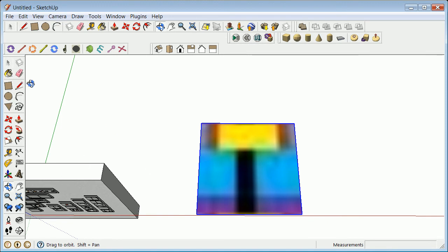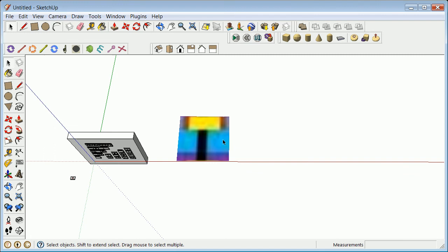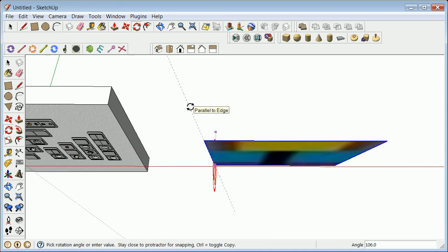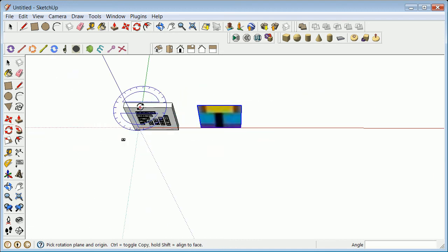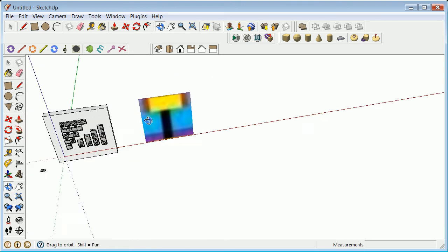Now I can do that same thing with that image. That came in as an image. And remember, in this program, you grab your tool, you grab the face and hold the shift key, and then you go to what you want to grab, select. And I'm going to turn that up 90 degrees. So I've got something there. Remember, in this program as well, you can then take an array of images. I'm going to do that just so you can see the difference.